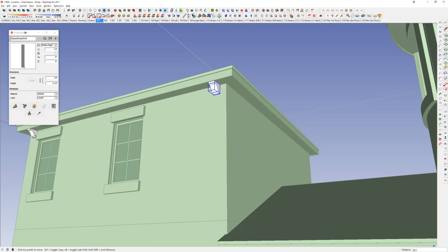And again, before I get out of the command, we typically do, say, 2 foot spacing on these brackets, or, again, just knowing what your brackets are for the project. You can do quick math. This is 20'4", and if I want a spacing of approximately 2 feet, you know that there's 10 spaces. So if I type in 10 divide, I just added in all those brackets.